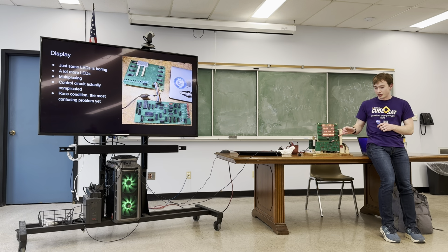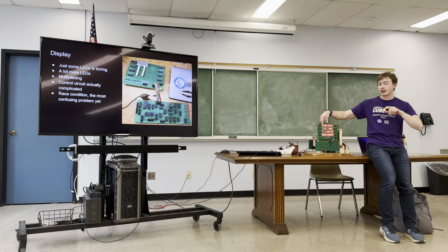And this is called multiplexing, by the way. Every time it shifts those 4 lines down, it has to load all the new data into the shift registers. These are very similar to the sequencer I showed with the bit moving down the line and then back. These are similar to that, but each of the outputs is connected to a whole column of LEDs.